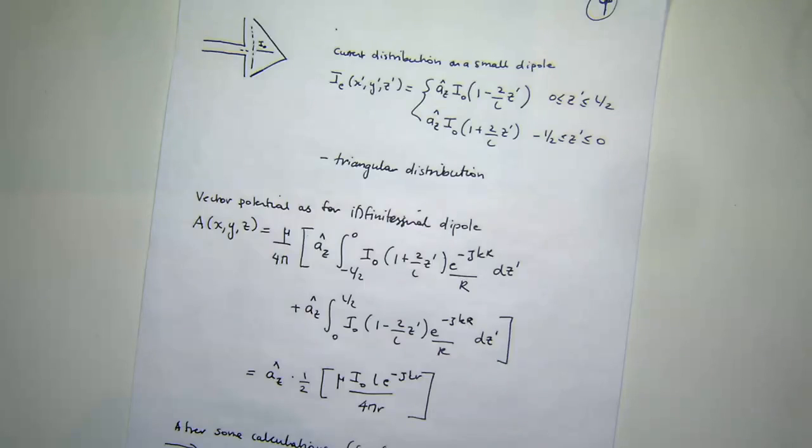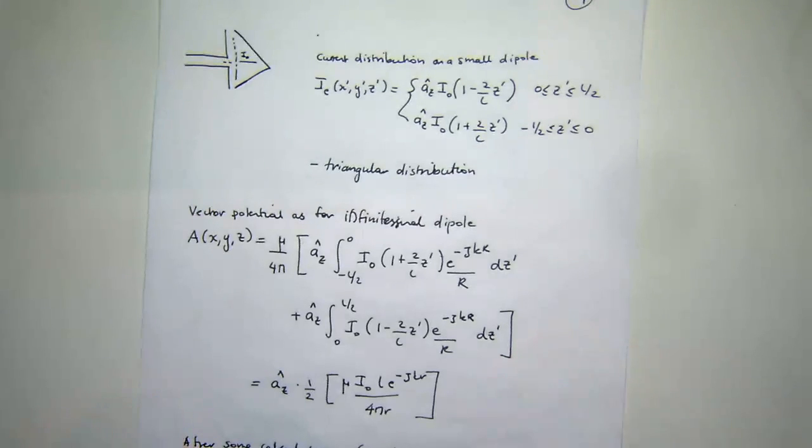Can anyone tell me what the directivity of an infinitesimal dipole is? Roughly. You can actually tell me in linear units or you can tell me in dB. We calculated it was roughly 1.5, so 10 times log of 1.5 is its directivity. Okay, now, why did we care about studying this infinitesimal dipole? Why did we study the infinitesimal dipole?